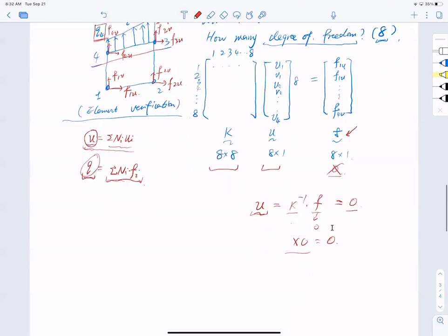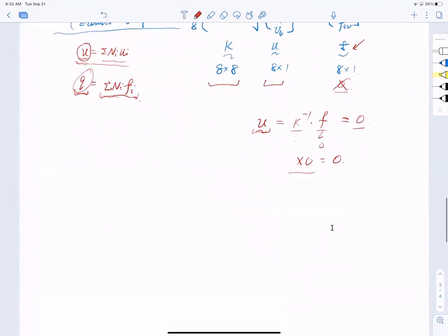Okay, so let me ask you this. What is the equivalence between the distributed load and the total force? Simply integrate, right? So integration of Q. The right-hand side is the total force, the left-hand side is distributed, so I need to integrate over the boundary and let it equal the total force, which is the summation of nodal forces. So they have to be equal.